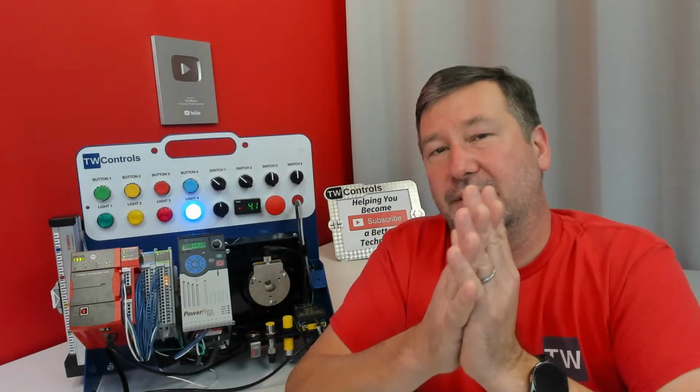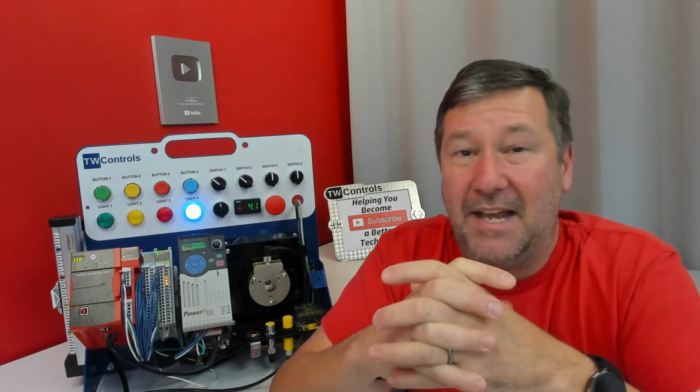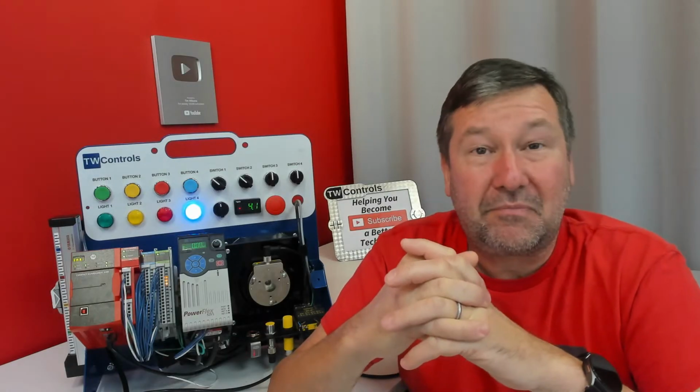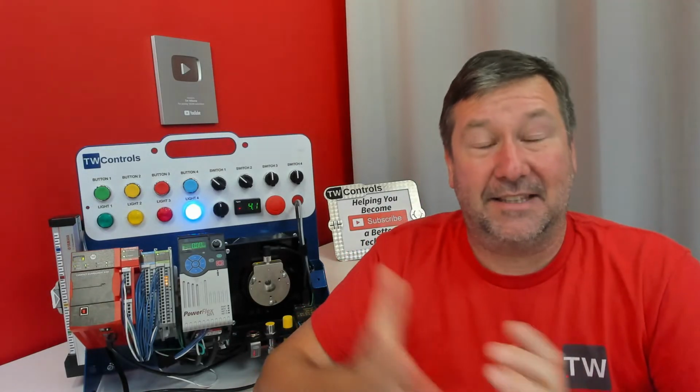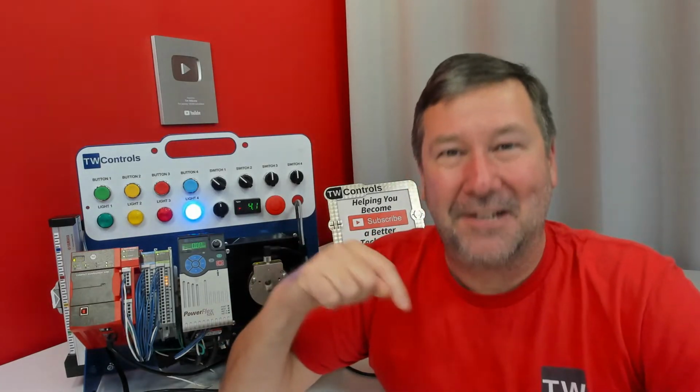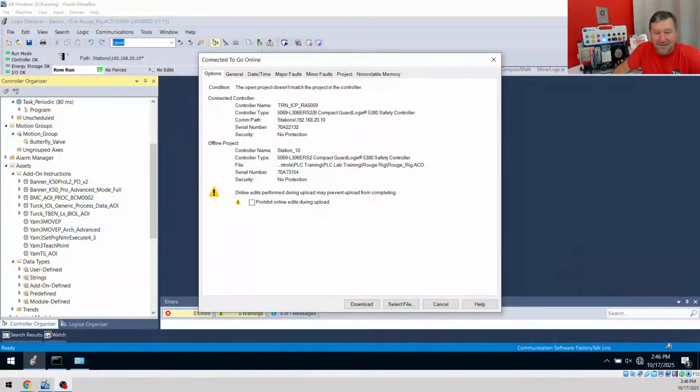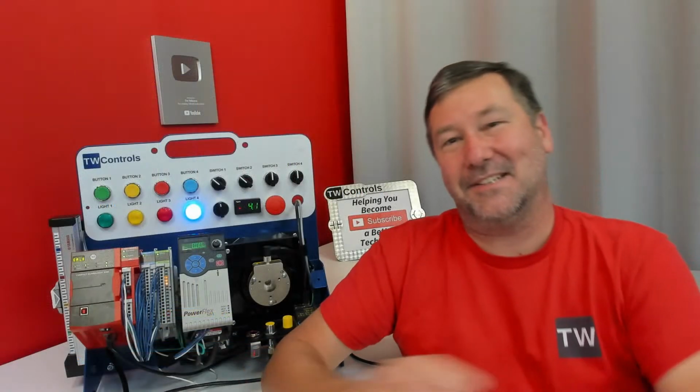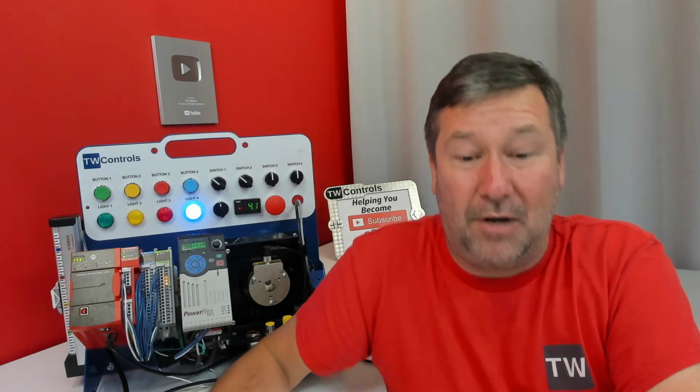Now, here's the important part: what if you get this prompt and they are the same serial number? I had a customer call me one day, and it was a really bad crash. And of course, they're blaming me. And I went out there and I got this prompt. And I'm like, well, wait, who's been online with this PLC? And of course, they're like, well, nobody has. Just get in there and figure out what's wrong with it. I'm like, no, somebody's been online with this PLC. This screen right here shifted the blame off of me, because I'm like, no, somebody has been online with this PLC. And even there, we got that prompt.